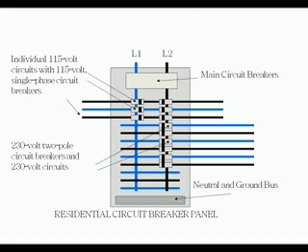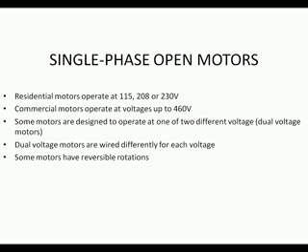Most typical residential panels provide either 115 or 230 volts. Commercial and industrial facilities require three-phase power. So if we look at a residential breaker, you have lines L1 and L2 coming into it. That's 230 or 240 volts. Each circuit comes off of it with 115 volts. The circuit is either from one or the other and is tied into the neutral bar as well. The 230 two-pole circuit breakers cross both lines 1 and 2 to make the connection.